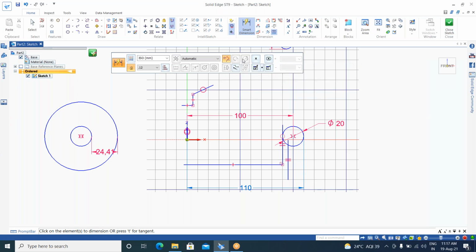So these are all the smart dimension angle measurements, and along with the dimensions itself, we can even give precision values. Here a prefix or suffix is available. I'm going to apply this inspection.